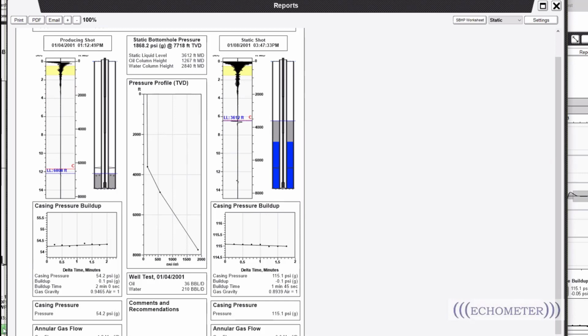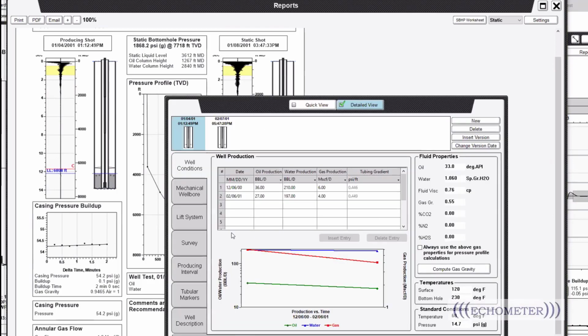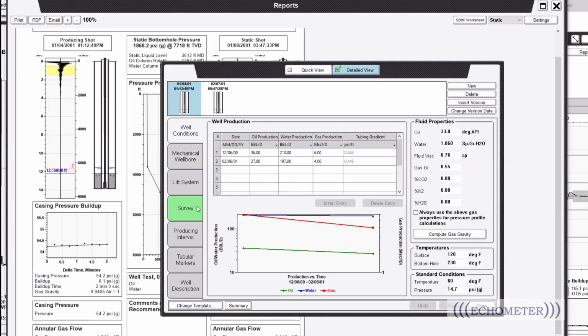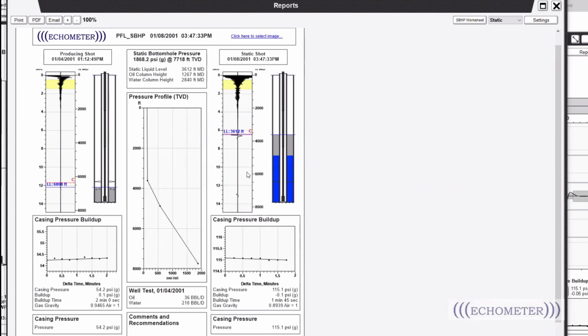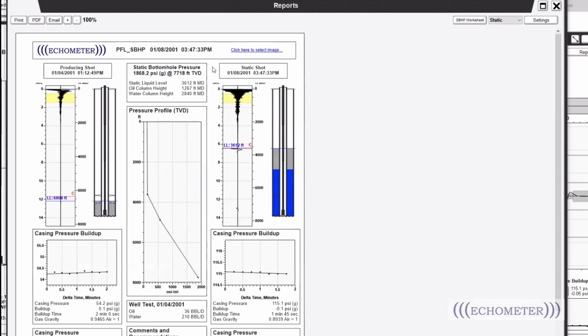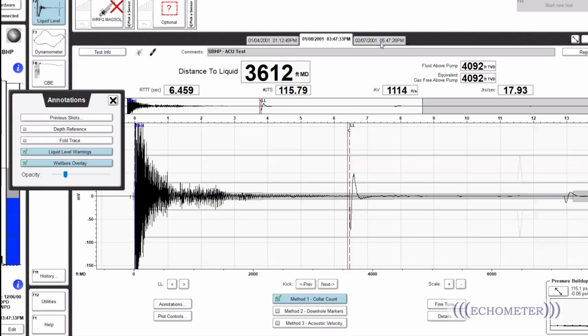This is a vertical well, and there was a question on where the survey is important to input in the software, for the ones who are not familiar with it. There was a question from Ken about an S-type well. And at this point in the software is where you can input the measured and true vertical depth, so we will calculate the equivalent true vertical column, distance or height, of each of these gas, oil, and water columns in the well. Something that we can review is that the software will use this information, but we need to be sure that we update the static borehole pressure information when we are analyzing the well after it's restarted.